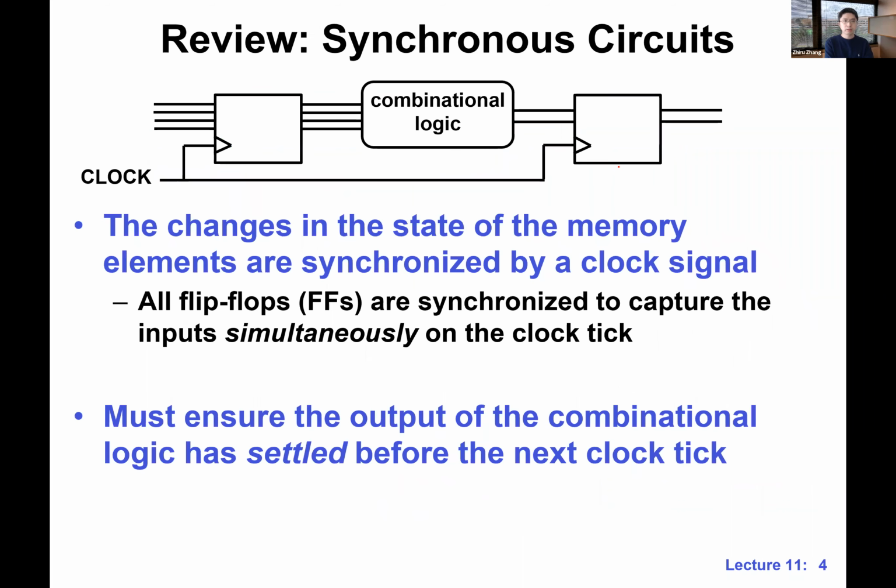And the reason we care so much about these flip-flops is that we are interested in using the so-called synchronous system. With a synchronous system, all these flip-flops are synchronized by a global clock. We update the states of these flip-flops at every clock tick, at every triggering clock edge. In our convention, usually we just use the rising edge. These are all synchronized, so we update the flip-flops simultaneously at each clock tick.